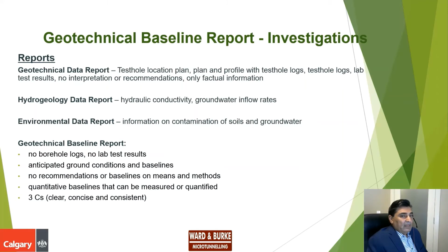So once the investigations are completed, then we have to prepare different reports. So first one is geotechnical data report, then hydrogeological data report, then environmental data report. So all these three reports, they provide only data, no interpretation, no recommendation.